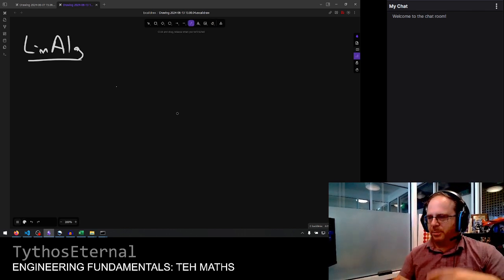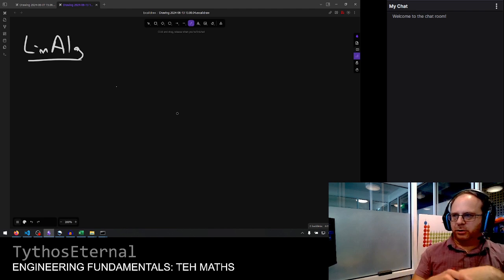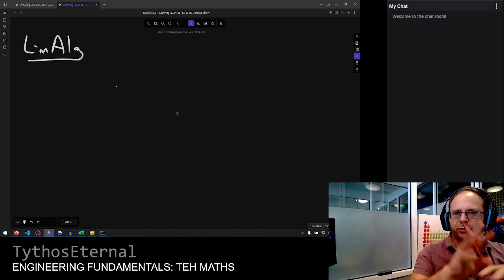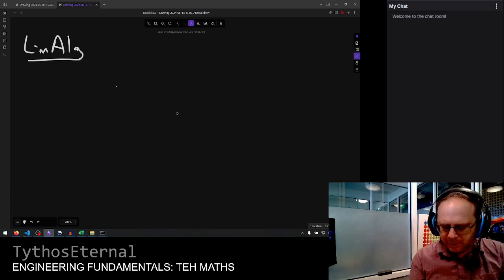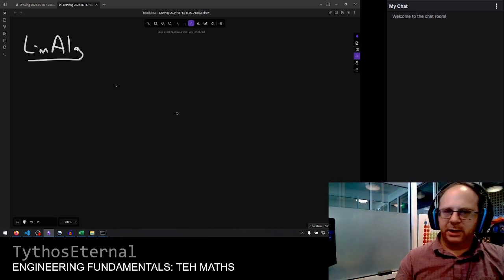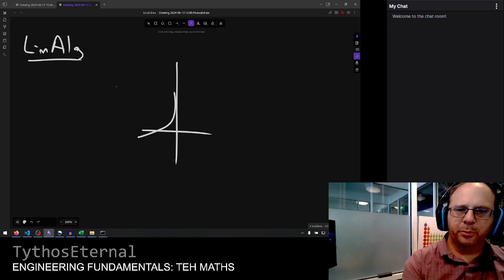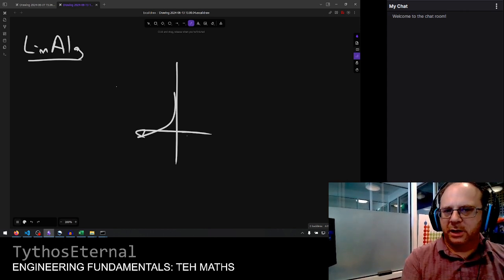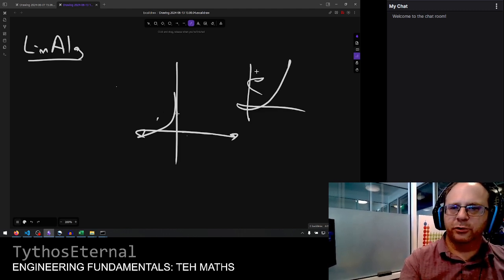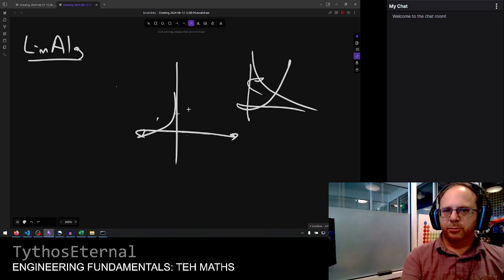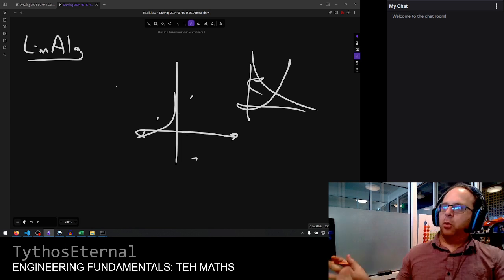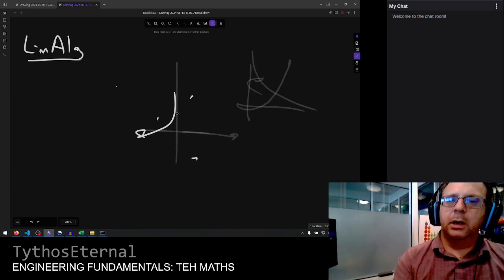And now it gives you very powerful ways, as you'll see when we get to controls, to be able to characterize how those roots and how the system response changes when you're able to move those around with tools like linear feedback. In particular, characterizing the stability of the system, being able to take it from an unstable domain into a stable domain, where you have positive roots that result in an exponential increase in system state versus negative roots that result in a stable one. So being able to move those roots around from that characteristic equation to the determinant is like the core of engineering and controls. All right.